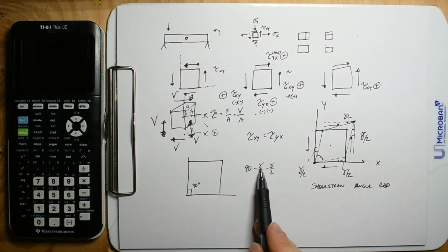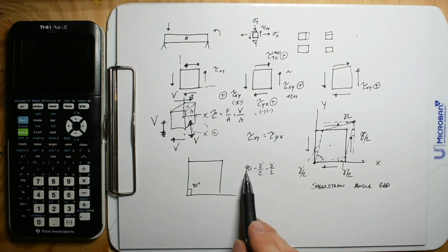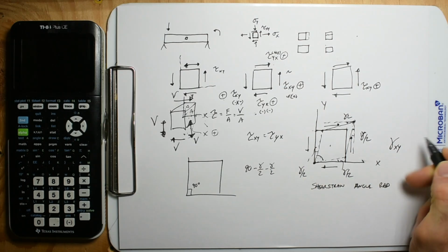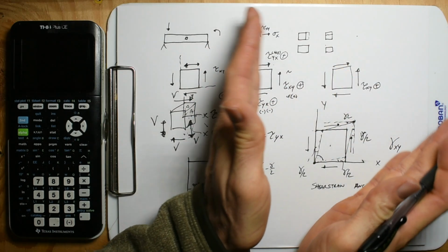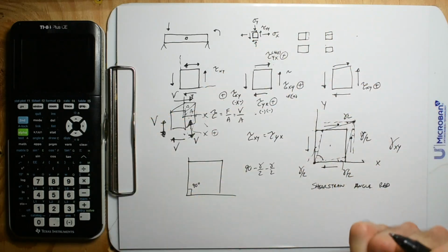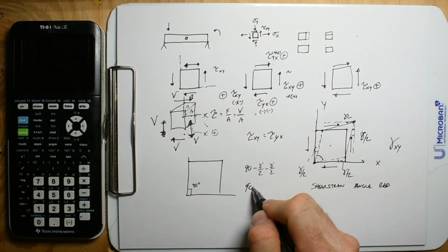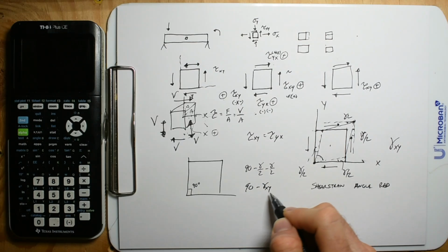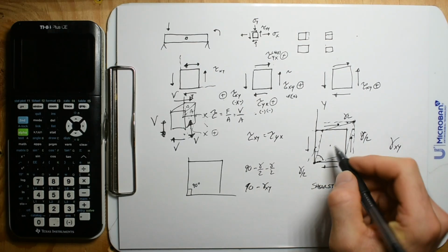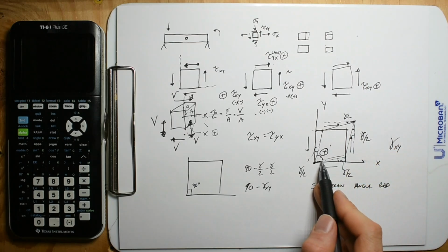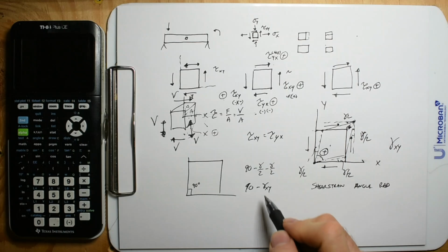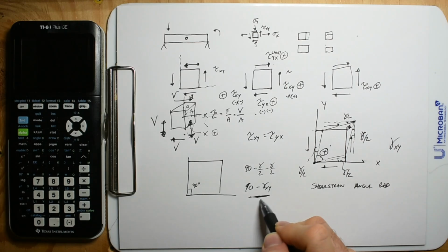This is the shear strain, so it's 90 minus the shear strain, and we could call this the shear strain in the xy plane because it's diamond shaping in the xy plane. It's not diamond shaping out of the board or anything like that. And so we just have 90 minus gamma in the xy plane. That is what's happening to this corner, and we're going to associate that with positive. And you can see that this corner is also a reduction. So that's what we're seeing.